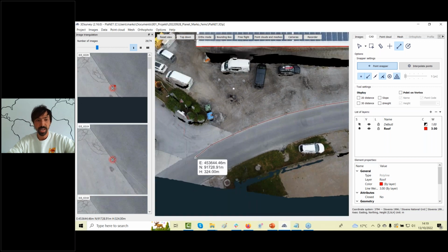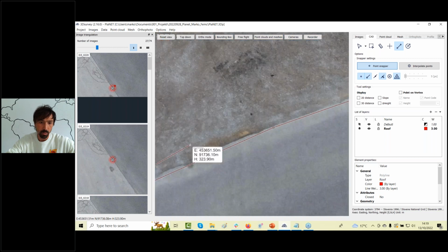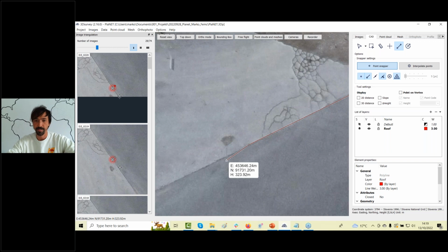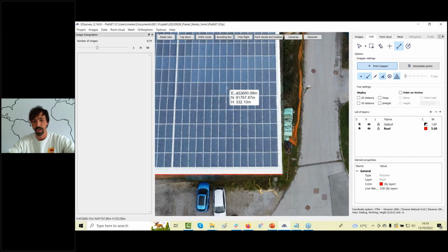So what's the main benefit here is definitely that image is the basic material which you put inside the processing, and the resolution of image is always the best one. So the point cloud cannot have that kind of good resolution. 3D texture, 3D mesh, because of texture, cannot have that kind of resolution. So I would say if you need really accurate position, this is a must have, and with this you can extract super hard details out from the 3D model with the help of photogrammetry.